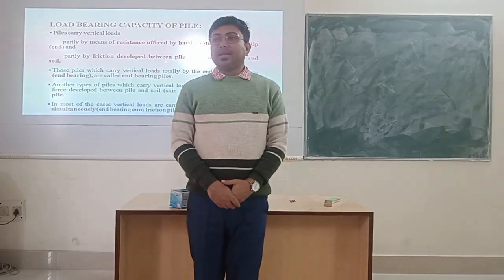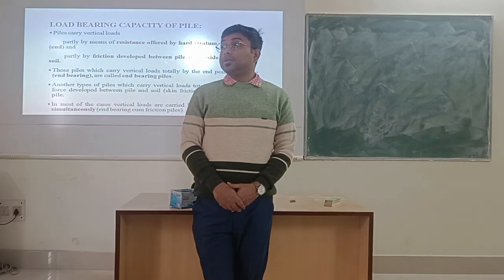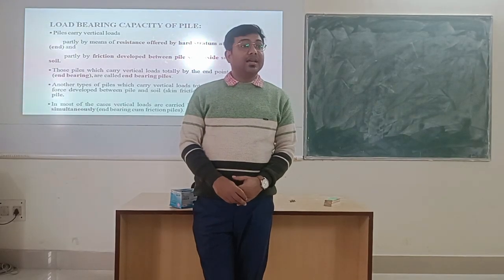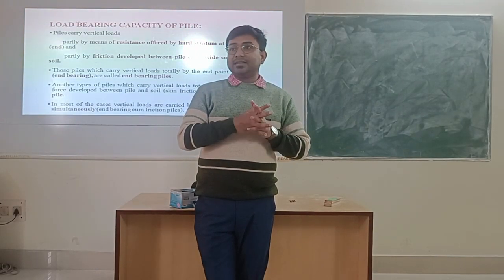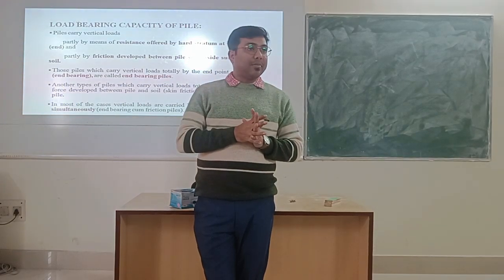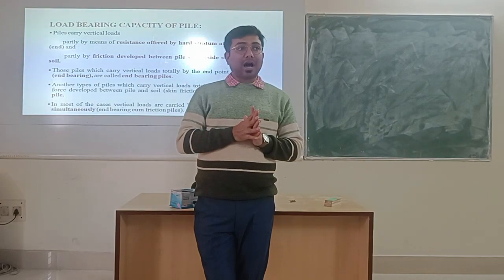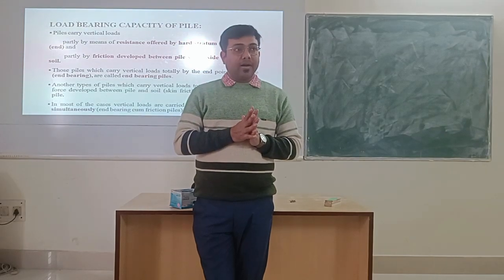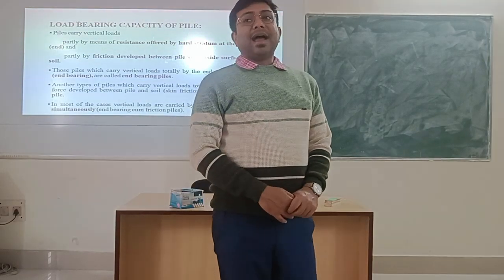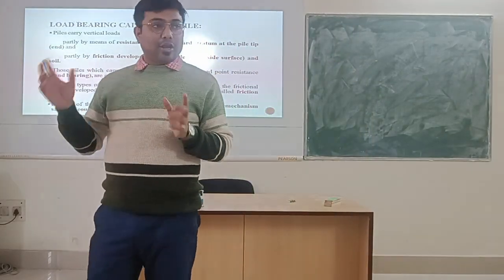The ultimate bearing capacity is equal to cNc plus gamma Df into Nq, plus half B gamma N gamma. Okay, so that was the bearing capacity of shallow foundation.